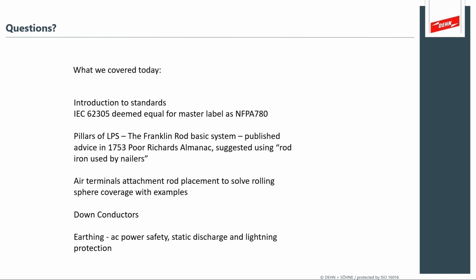So a lot of the question comes back to, what is the impedance of an individual rod, and how do I build a system that has an equivalent electrical impedance into the soil? That exercise is actually very detail-oriented, where you'd have to get your soil resistivity, understand the conditions, and then start placing your earth electrodes relative to where your down conductors are going to be as well. There are a lot of simultaneous factors that all have to be solved and satisfied.